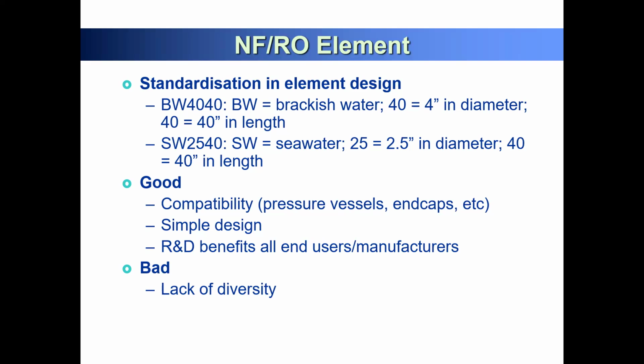So you have an 8-inch diameter, about 20 centimeters, of your spiral module. The length is 1 meter. And then what's the surface area of this membrane? So you can calculate what kind of membrane standard we have to utilize from this.